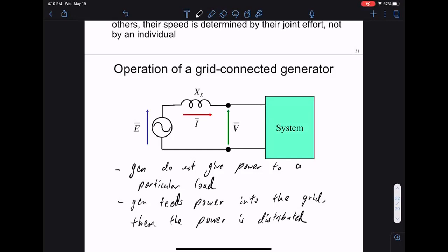So Alex asked, do you need to match the phase of the generator? Yeah, you need to match the phase, or make sure the phase is not off by too much. So phase matching is fairly simple, right? We're very good at measuring the phase of an AC signal. You can think of a phase lock loop. If you figure out what the phase of the grid is, then it's just a matter of changing your rotor phase to time it such that you match the grid. You can do that through several cycles. So you cannot change phase immediately, but it takes a few seconds, and you can match phase to the grid. Measuring phase from the grid is not terribly challenging nowadays.